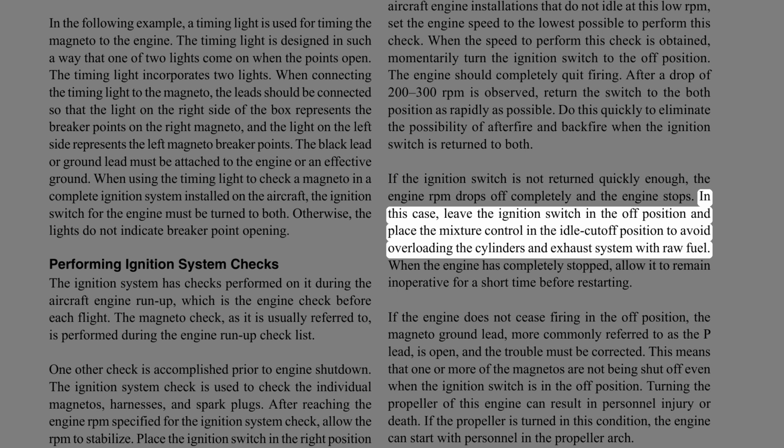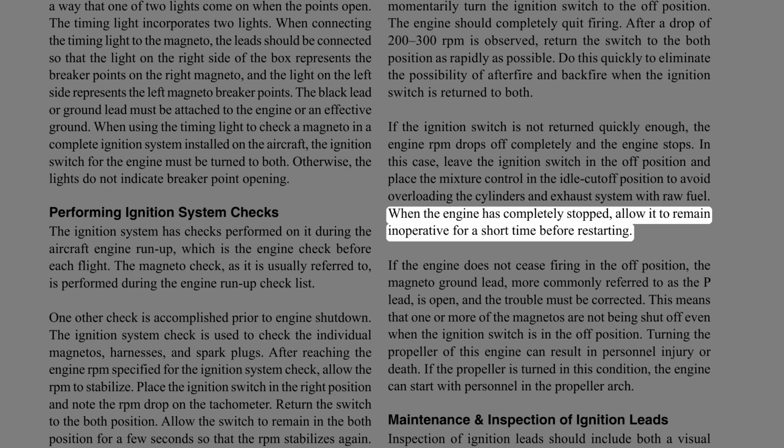In this case, leave the ignition switch in the off position and place the mixture control in the idle cutoff position to avoid overloading the cylinders and exhaust system with raw fuel. When the engine has completely stopped, allow it to remain inoperative for a short time before restarting.